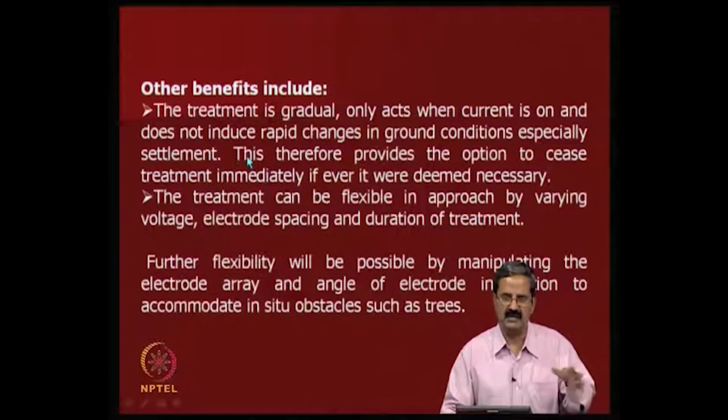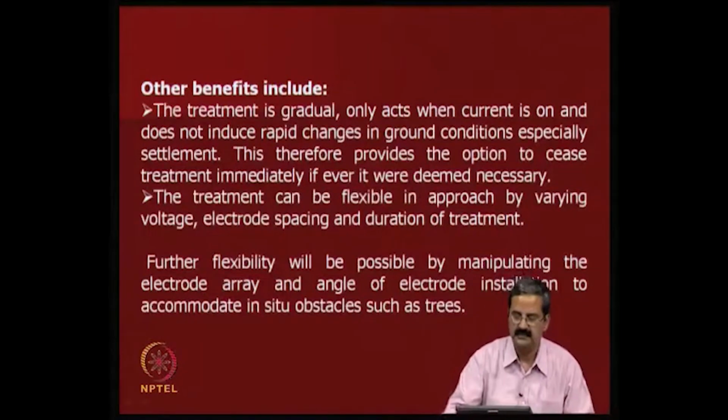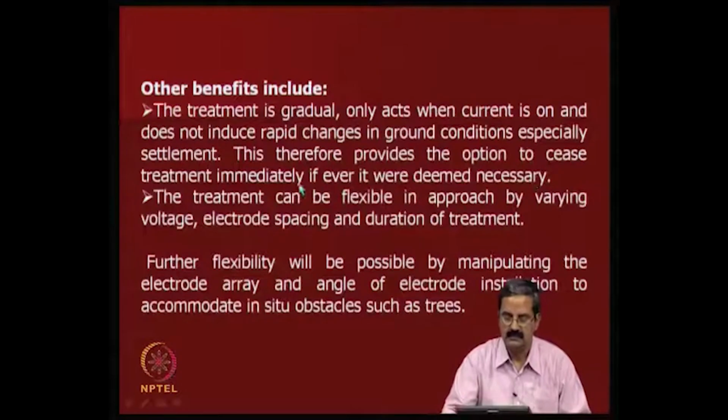Whatever settlements we were thinking of in the earlier stages, because of changes in effective stress, are not there here. It is because of the changes in pore water chemistry, changes in the soil structure and all that. This is much more efficient. And the treatment can be very flexible in approach, by varying voltage, electrode spacing and duration of the treatment.